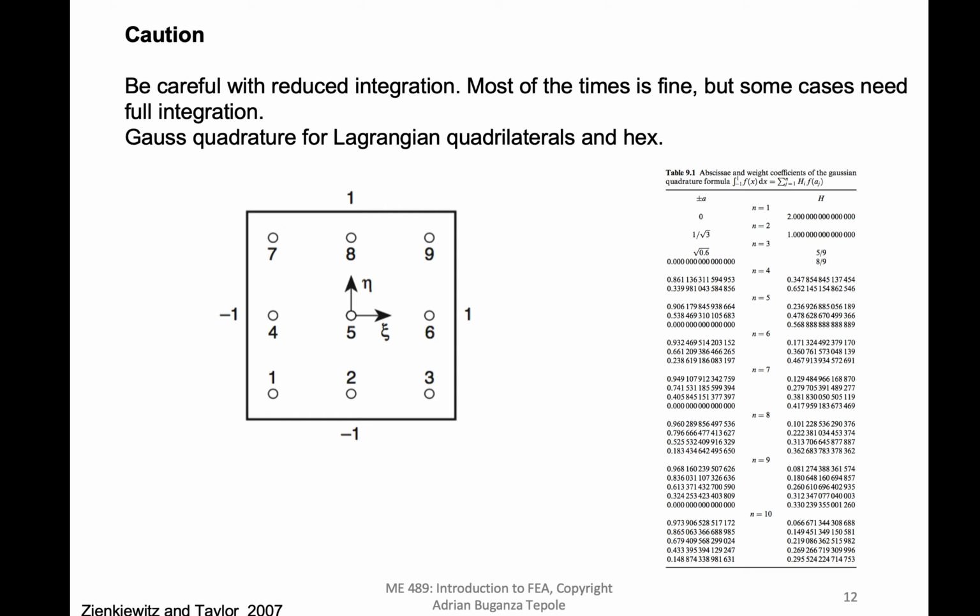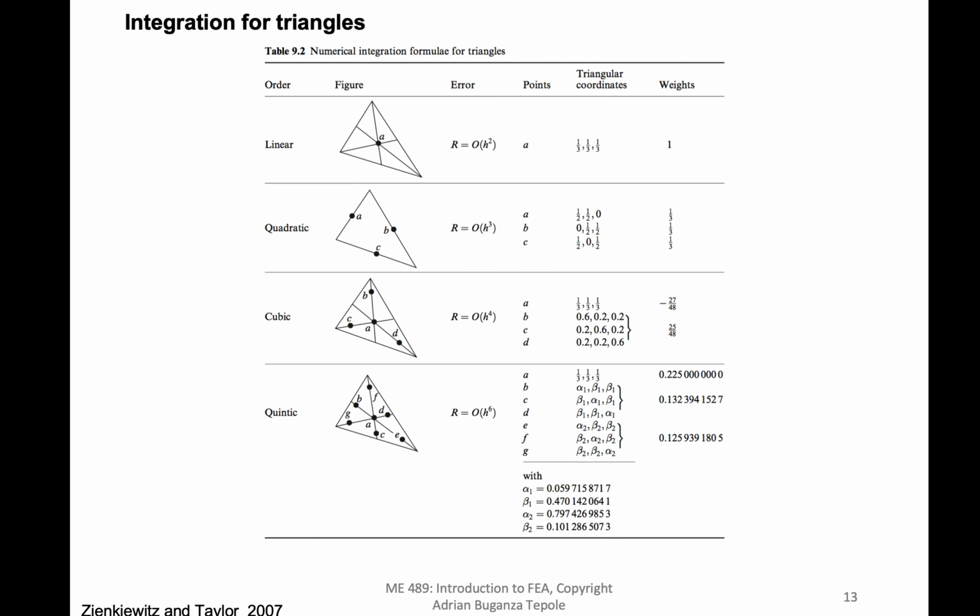And this is something that we did in particular within Abaqus. We did this one lab of the shear force at the end of a cantilever beam, and then we tried the different elements. For example, there we showed how the reduced integration elements had some trouble because they had some modes of deformation that didn't take any energy. So by doing the reduced integration, we were basically making the element too compliant. So that's something just to keep in mind.